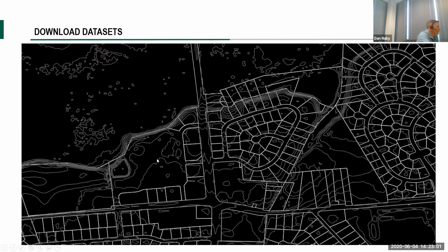So you'd be able to see what the general elevations are, what the general drainage patterns are, and those sorts of things. Again, a good jump start on having some information to be able to intelligently lay out a site ahead of having to go with a full topographic survey and the time and costs associated with that.